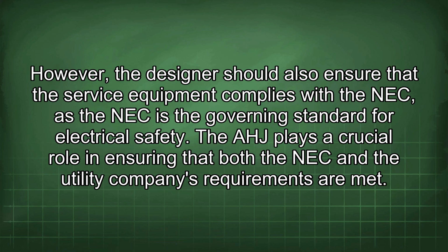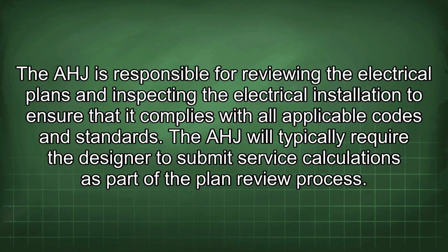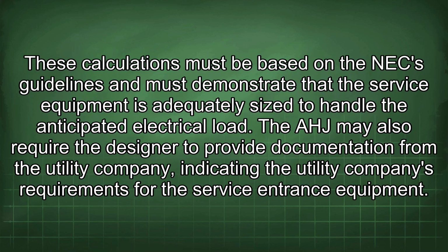standard for electrical safety. The AHJ plays a crucial role in ensuring that both the NEC and the utility company's requirements are met. The AHJ is responsible for reviewing the electrical plans and inspecting the electrical installation to ensure that it complies with all applicable codes and standards. The AHJ will typically require the designer to submit service calculations as part of the plan review process. These calculations must be based on the NEC guidelines and must demonstrate that the service equipment is adequately sized to handle the anticipated electrical load.